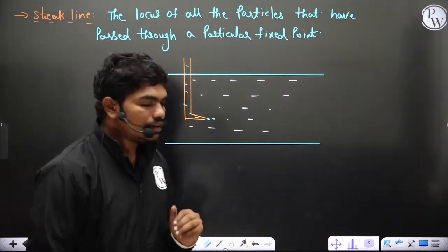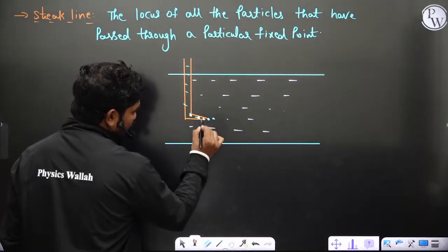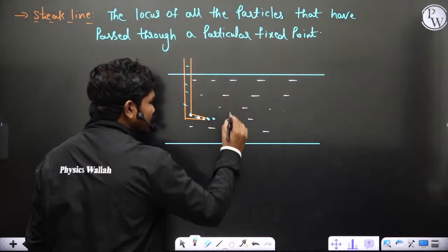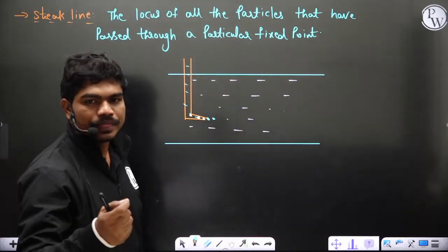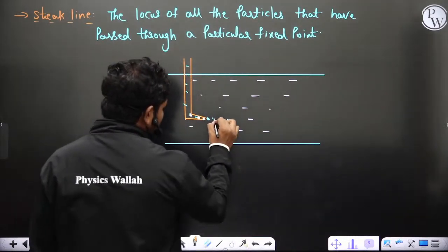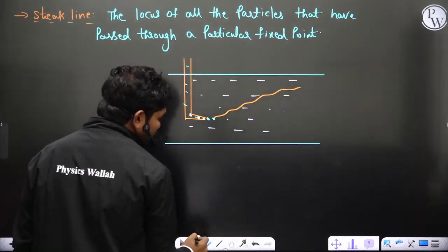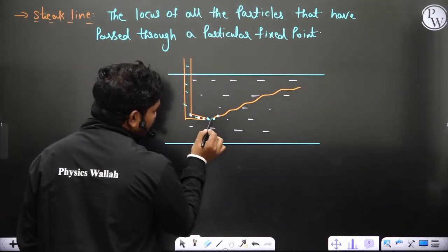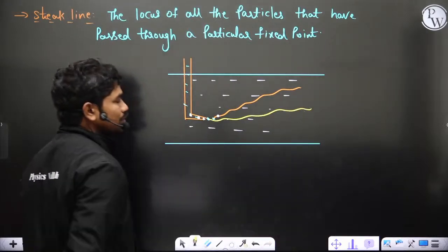So whenever these particles are floating or moving, they will move as per the movement of this flow. What I'm telling you is, if you start injecting some small dye particles into the flow, these particles will be taken up by the flow, and if the flow particles are moving in this direction, these dye particles will also move in that particular fashion. Now try to understand one thing. Let us suppose this first particle has moved like this. Whenever the first particle has reached from here to here, the second particle gets out of the injector and let us suppose this second particle moves something like this.